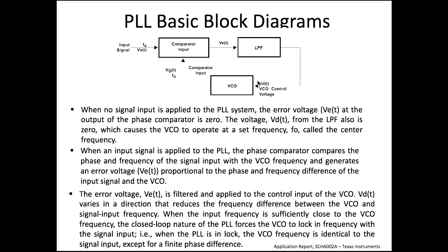Then when the VCO input changes, the frequency will increase accordingly. See, this frequency will increase, and then again we take the difference, and this error may be less. And so on. After some time, your data frequency and this PLL frequency will be matched, in a couple of loops. Another advantage is both will be synchronized.